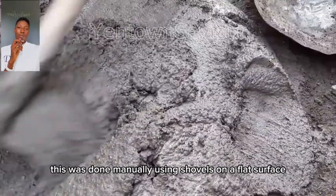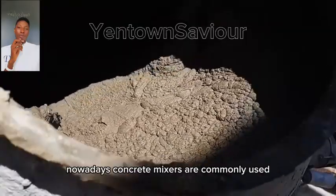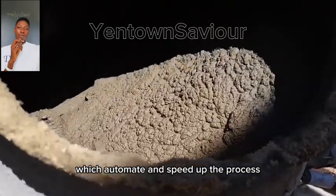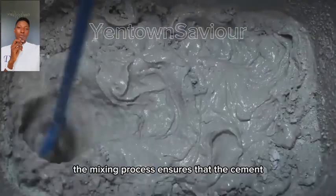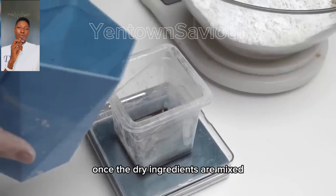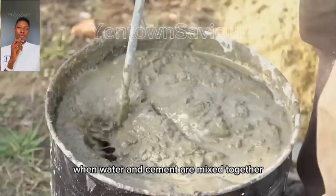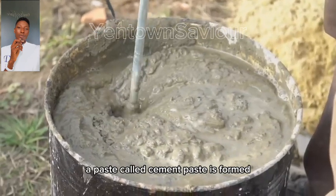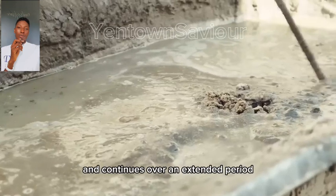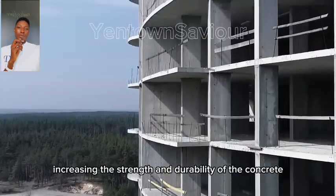Traditionally, this was done manually using shovels on a flat surface such as a concrete slab. However, nowadays, concrete mixers are commonly used, which automate and speed up the process. The mixing process ensures that the cement particles are evenly distributed throughout the aggregates. Once the dry ingredients are mixed, the water is added gradually while continuing to mix. When water and cement are mixed together, a paste called cement paste is formed. The hydration process generates heat and continues over an extended period, gradually increasing the strength and durability of the concrete.